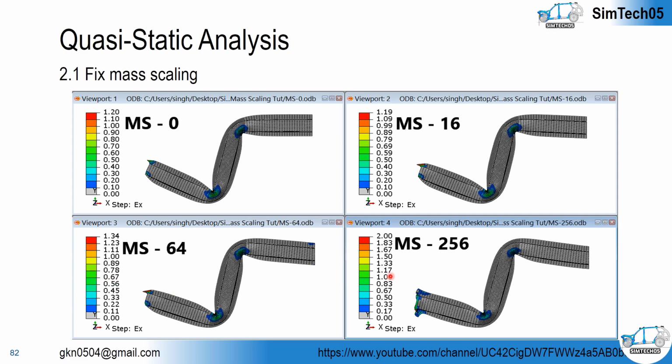But in the third and fourth cases, the results, or we can say the equivalent strain, is varied, and this is not acceptable. But you don't even know whether this simulation is accurate or not if you do not perform this simulation within the actual time, or we can say without any mass scaling or increased load rate.